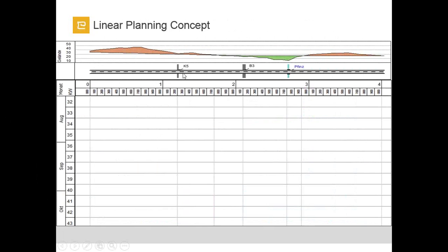For example, here we have our pictorial view, which shows the total scope and some working limitations, as well as geographical information. We know that we have a two-lane new road construction with 2 intersections with other roads. We also see that we have a river, so we know we need to build a culvert at this chainage.